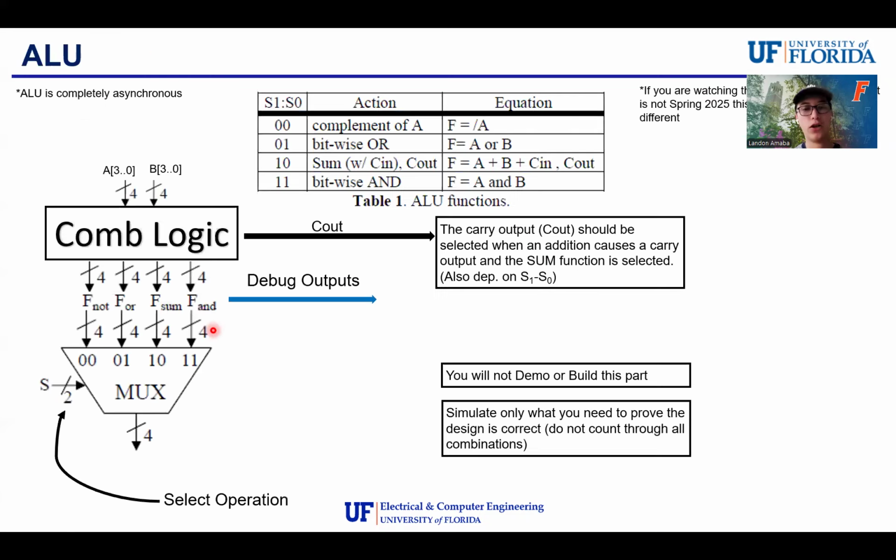All right. So to get started with the ALU, an important thing to note is that the ALU is completely asynchronous. So what this means is that there's no clock input, and depending on when you change the inputs into your system, it'll automatically change your outputs. So you can see here, this is the block diagram that's given in your lab document. And then I basically added this smaller block diagram above it.